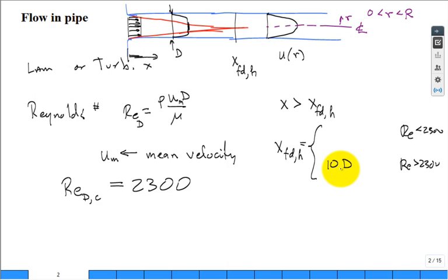And so one of the classic things in a plant is where do you put the flow meter? If the flow meter assumes that it's fully developed turbulent flow, where you put the flow meter, you look upstream of that flow meter and make sure you have 10 diameters. And I've seen cases where they don't. And then they have bias in the flow meter readings for the life of the plant, whenever it's running. And so take that away.